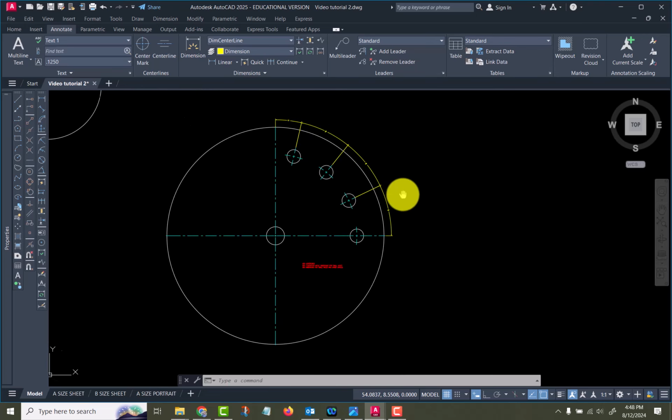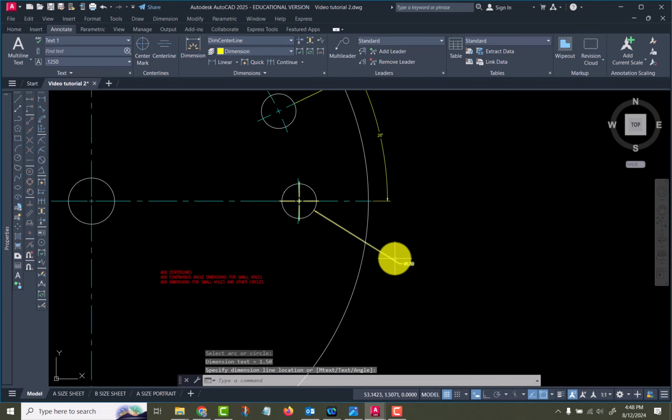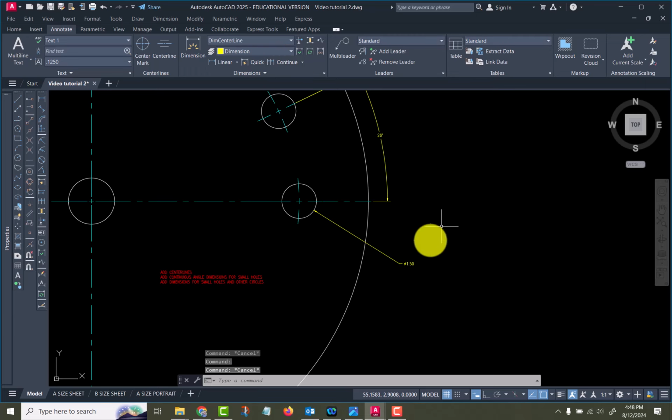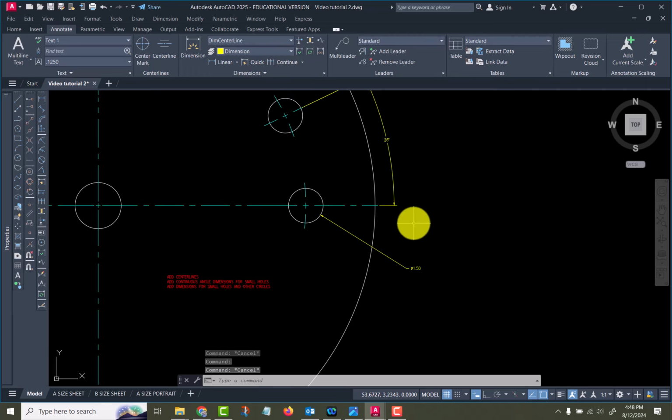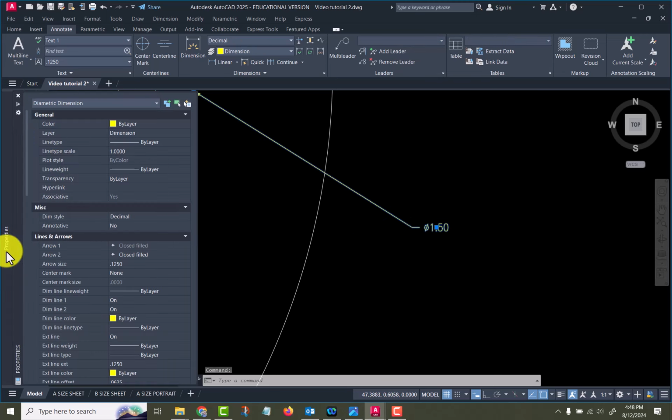But now then, dimensioning our circle, we're going to go with a diameter dimension off of here, and we'll pull it to the outside. Oh, I'm on the wrong one. You see, it put my centerline pattern in there because I didn't change my dimension style. Okay, there we go. Now, I've got a diameter of 1.5, but I've got 4 circles, and they're on a bolt pattern, a bolt center pattern. So what we'll do is we select this and we go to Properties.